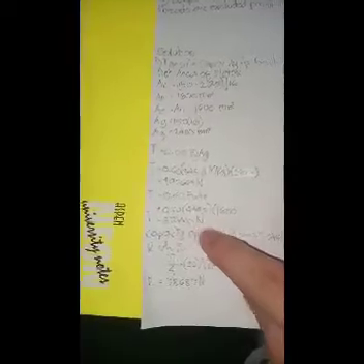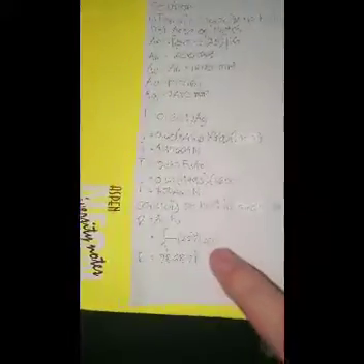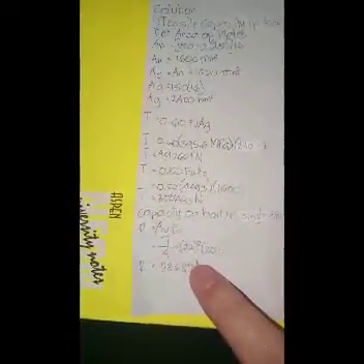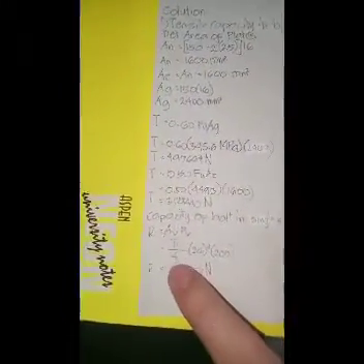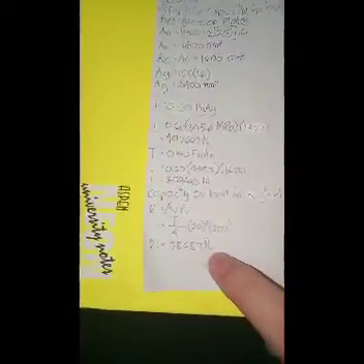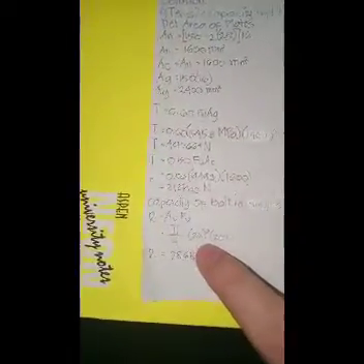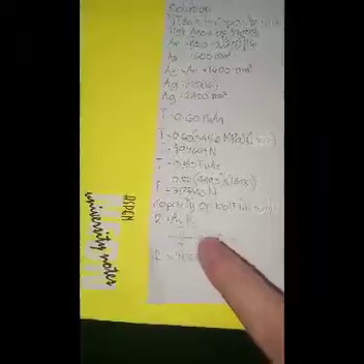Then, capacity of bolt in single shear. First things first, R is equal to A sub b times F sub v. So, pi over 4 times 22 raised to 2, times 207 MPa. Our answer is